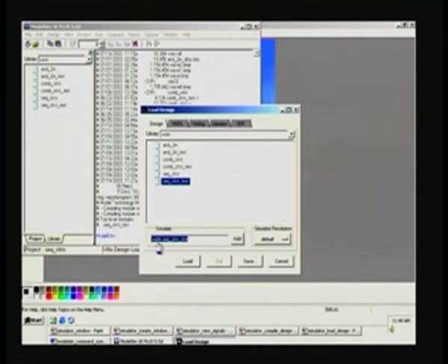Now, you see work.sequential_circuits_test, the top module is sequential_circuits_test, but you are working in a separate directory called work, and this is mandatory as I mentioned earlier. It is precisely the same here, that is the library; sometimes if you click here you may not see this, so make sure that it is in library. Now the next step is to load this, so press the button load.